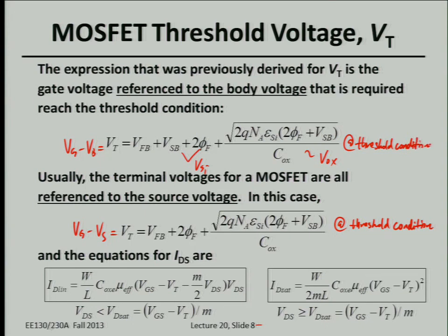So just pay attention here. Also, the derived equations for the drain current in different regions, we can re-express as a function of the gate bias, the redefined threshold voltage, as well as the drain bias. And the further corrections will be made at a dependence of the drain bias, which results from the spatial dependence of the depletion charge, right?